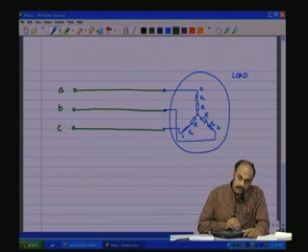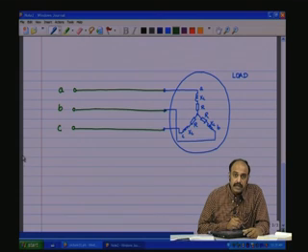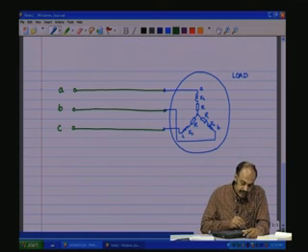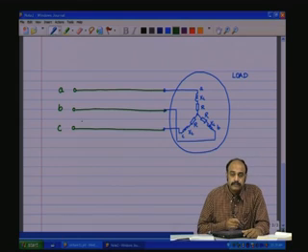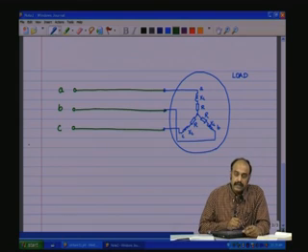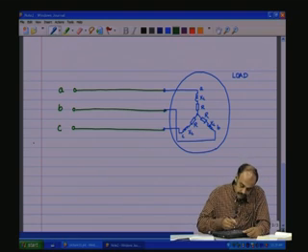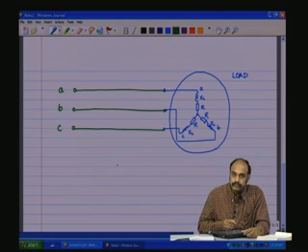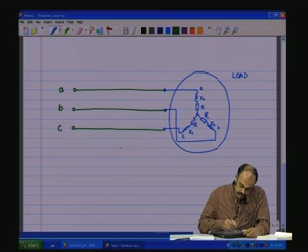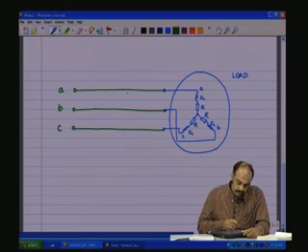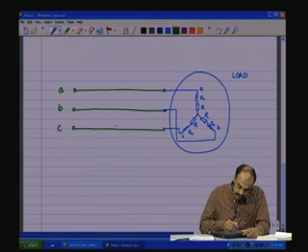So, in order to reduce the reactive currents that are being drawn from the source side, so that the ratings of the source or the generator can be more optimally used, normally in the industry, they try to improve the power factor from the line side by connecting a capacitive kind of a buffer in between, to act as a reactive generator.